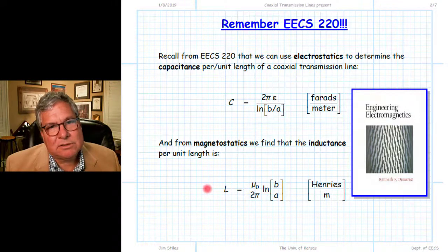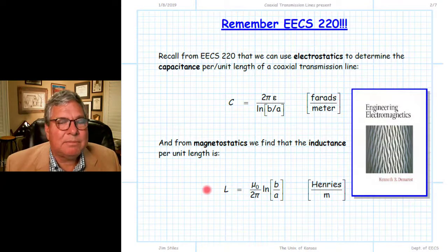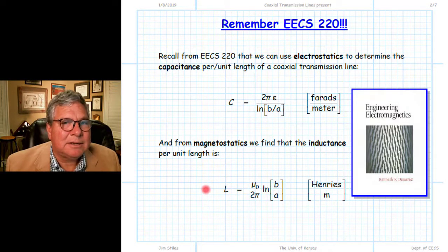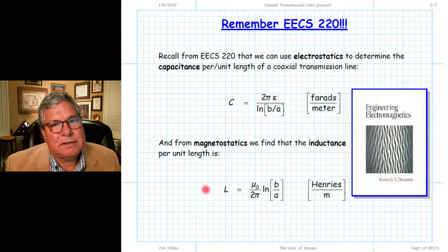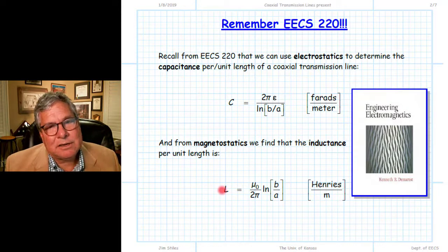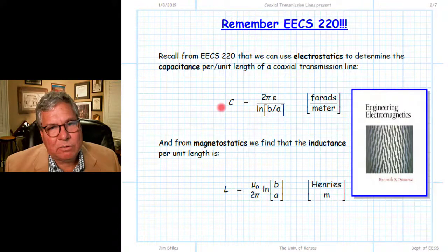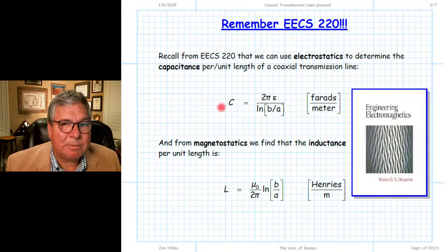the currents and voltages that we are using are of high frequency. And this really sort of requires us to distinguish what we call a transmission line from simply a couple of wires. If we have high enough frequency that the induced voltages due to the inductance are significant and cannot be ignored, and the displacement current from the capacitance is significant and cannot be ignored, then we need to figure out what the capacitance and inductance per unit length of these wires are.